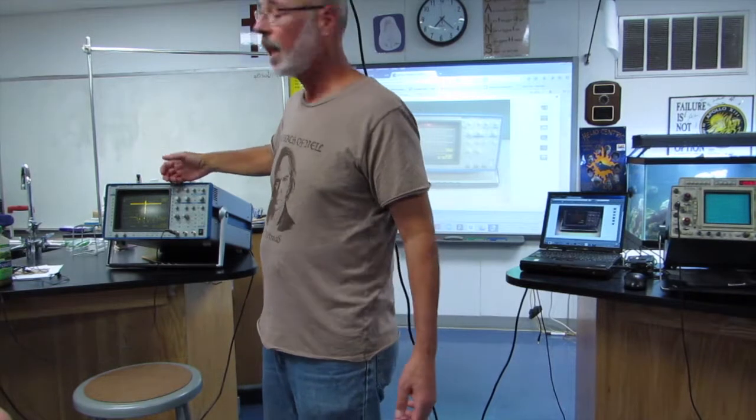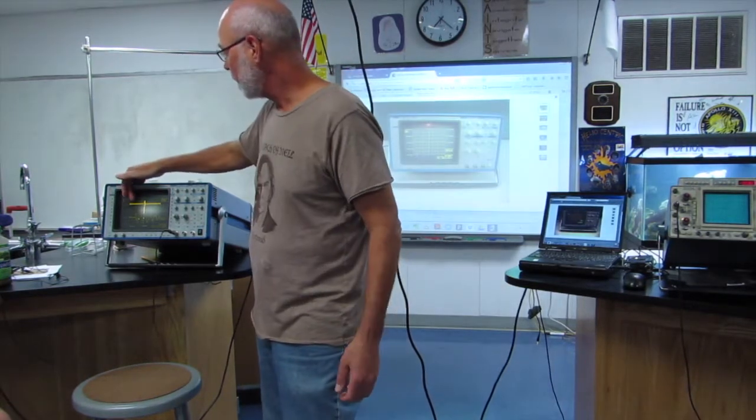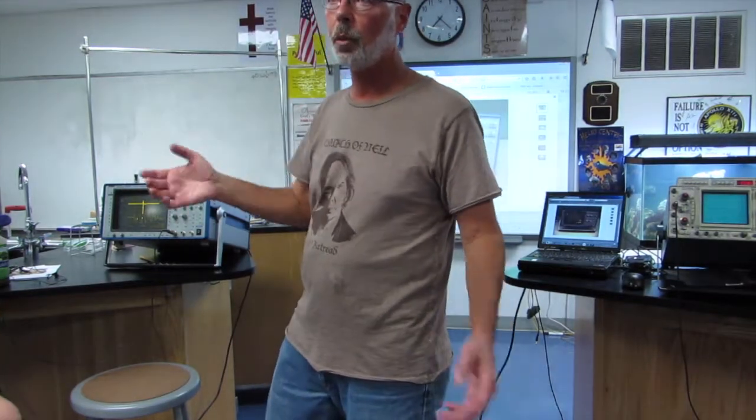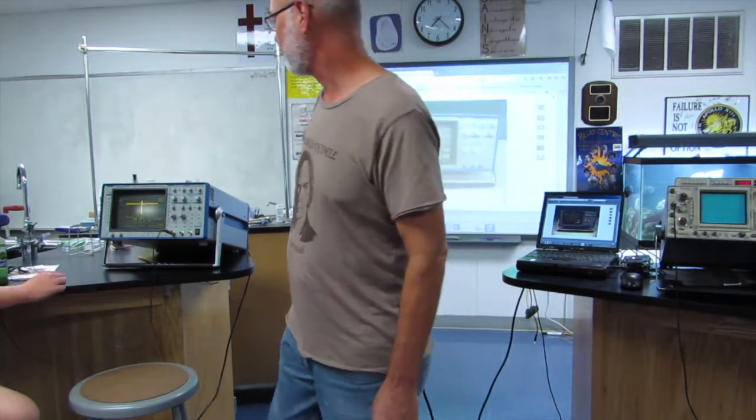This scope here is 125 megahertz. Even though it's a digital scope, that gives you an idea of the speed of the RAM. The RAM fills up at a rate of 1,000 points at 10 nanoseconds per division. It will write about 1,000 locations in 100 nanoseconds, so it's very, very fast. This scope will easily display 100 megahertz signals and record them at that rate.